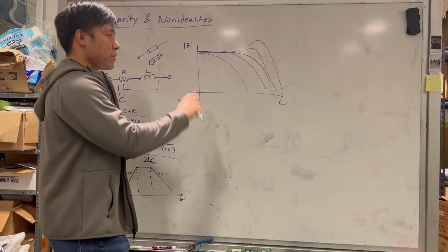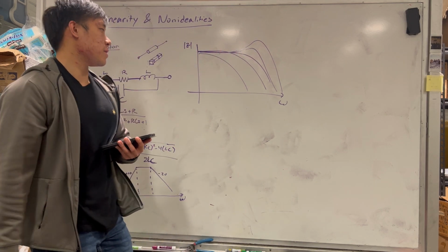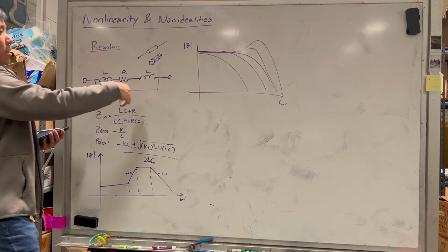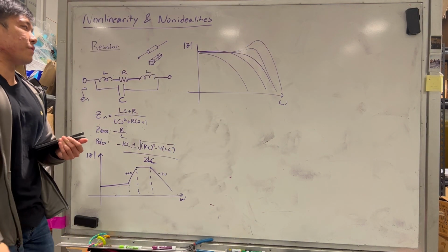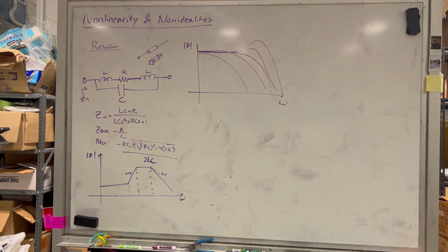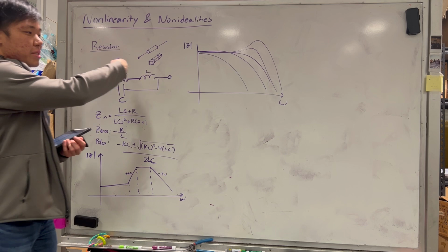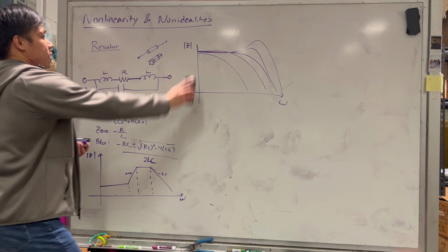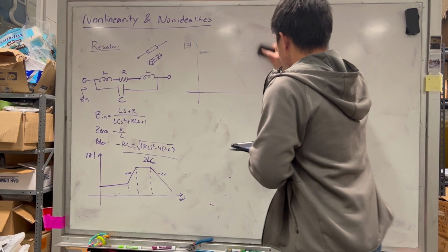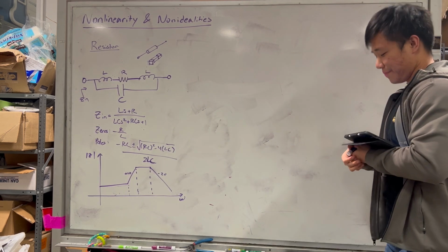So the smaller and smaller your resistances, the further out you can push it, but there's gonna be some resonance peak due to this LC resonance. But the larger the resistance you use, the faster it'll get rolled off. So at higher and higher frequencies, you don't want to use bigger and bigger resistances because effectively the particulates that are used to construct the resistor will short out your resistor. And so you won't actually see a resistor at higher frequencies. So that's some effect that you want to take notice of. So that's for resistors.